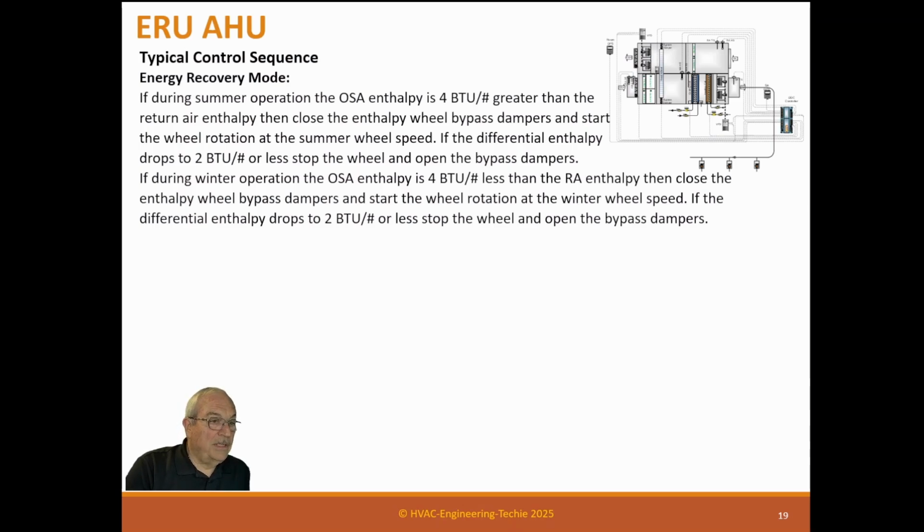And that's why we needed those humidity sensors where they're at, so we can tell what the enthalpy is going through it. We calculate enthalpy from dry bulb temperature and the humidity of the air. And those sensors are easy to use. Now, the one thing about this sequence is it is an enthalpy wheel. And to keep this operating correctly, these humidity sensors need to be calibrated often, probably every 6 months. And this thing needs to be checked every season to make sure it's operating correctly.